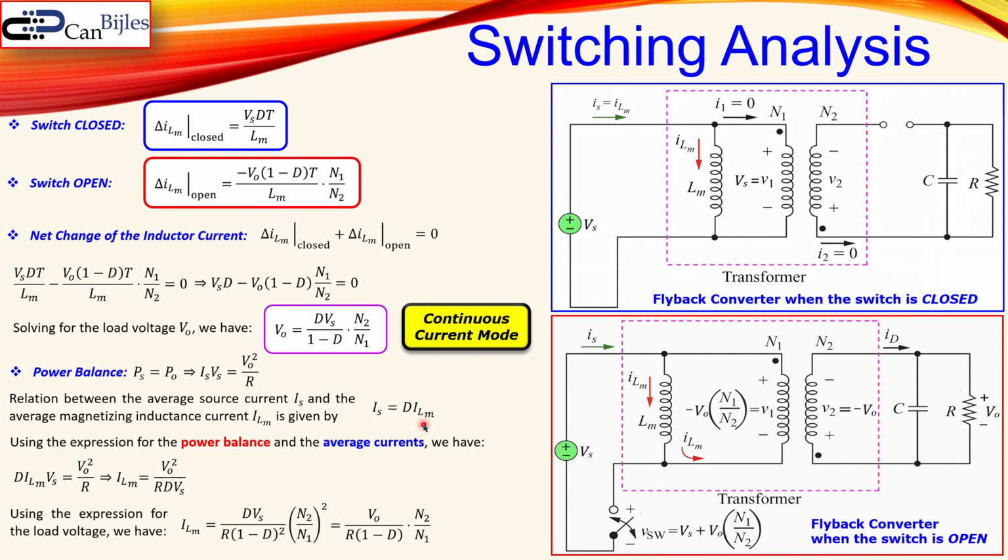Okay. You can also have it in a different form because this can also be written like so. So you have the VO here and there's also the ratio here in a duty cycle and the resistor. So if you make your resistor larger, you can have your average current here smaller. And depending on the ratio, of course, you can control the average current of your magnetizing inductance.